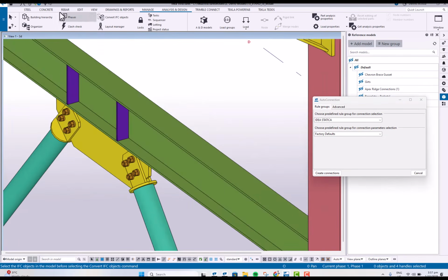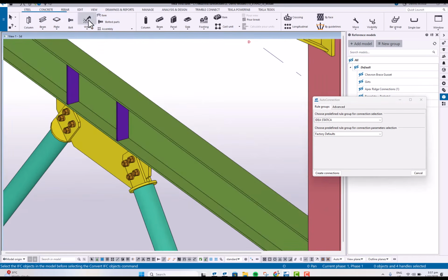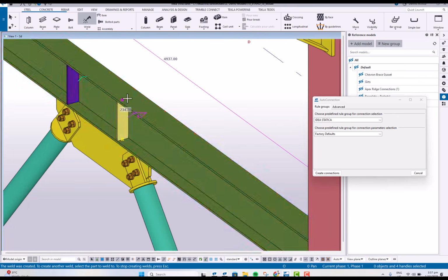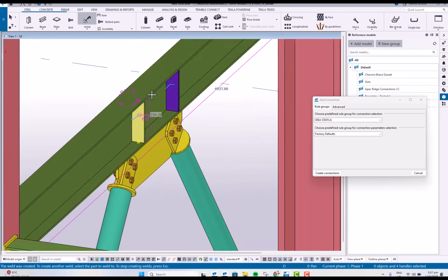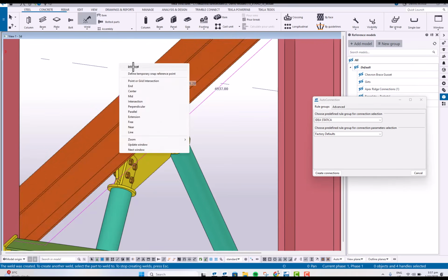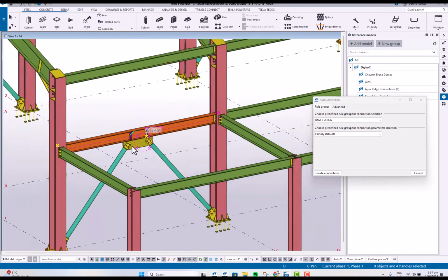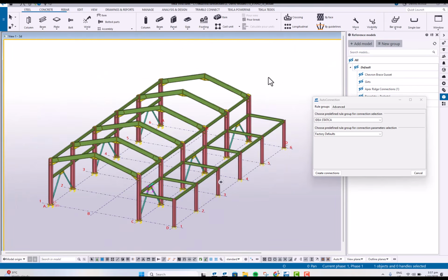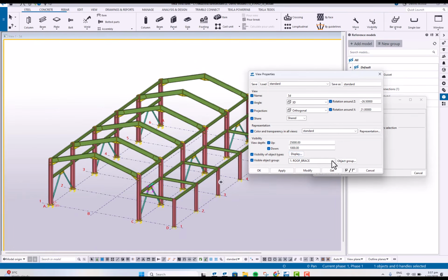So this one, all I have to do is go to my weld, and then select the welding so that it will be part of my assembly. So later, when we create the drawing, that will be part of the assembly drawing. Okay? Now, to continue, I can also open the roof brace.